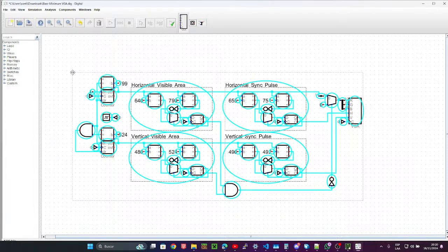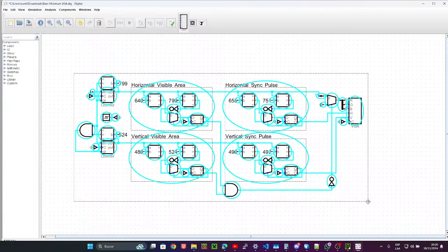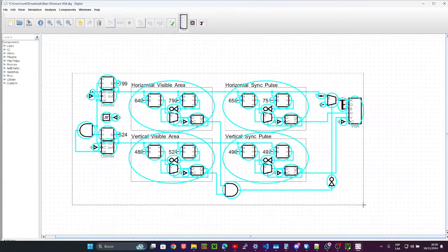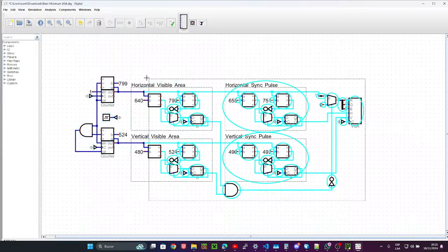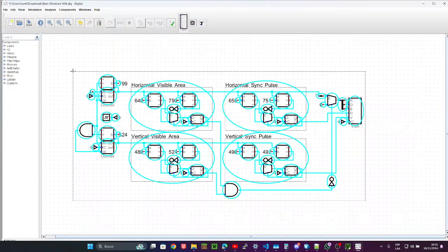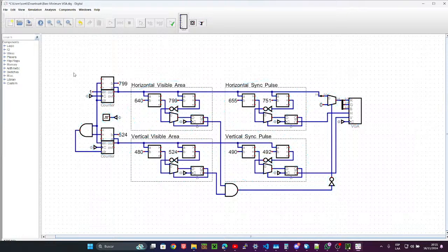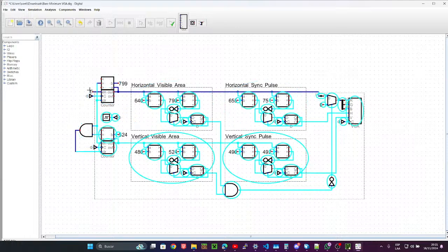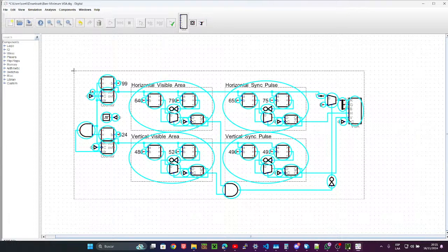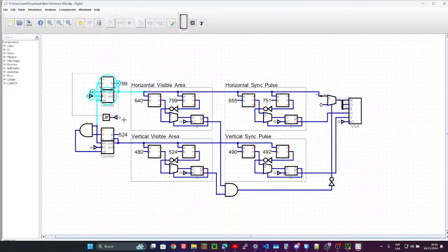It dropped from 307 kilobytes to barely 10. But of course, now you can only have a set amount of 8 by 8 pixel patterns, right? Yes. But if you just want to display text, you just draw a font, put it on a block RAM, and then just refer to it with another block. It's really nice. If you just want to display text, it is a very good solution.